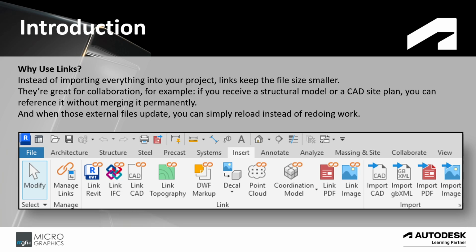In the Insert tab, you'll have Manage Links on the left-hand side. That's where you can manage all the links: how you control them, inserting them, reloading them, and removing them. And then you have the Link panel with all the different file formats that can be linked, and you get the import options there on the right-hand side of your screen currently.